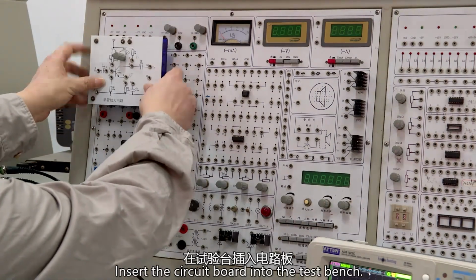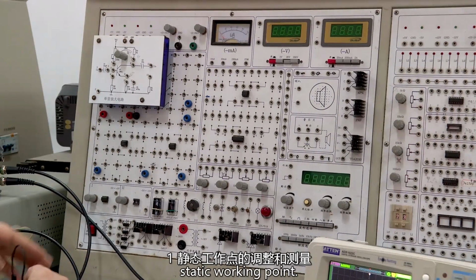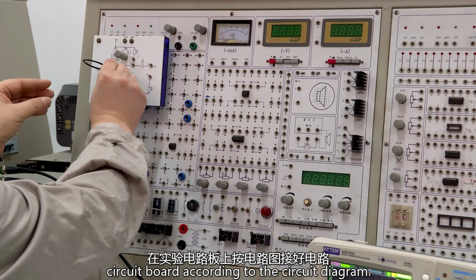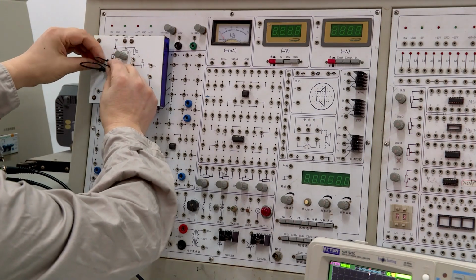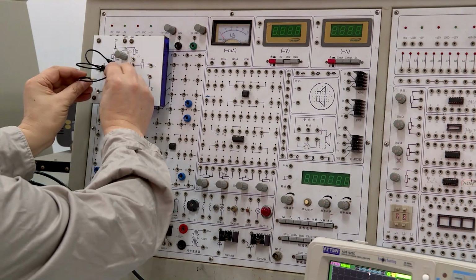Insert the circuit board into the test bench. 1. Adjustment and measurement of the static working point. Connect the circuit on the experimental circuit board according to the circuit diagram. That is, connect holes 3 and 5 with a wire. Connect holes 4 and 5. Connect holes 5 and 6.